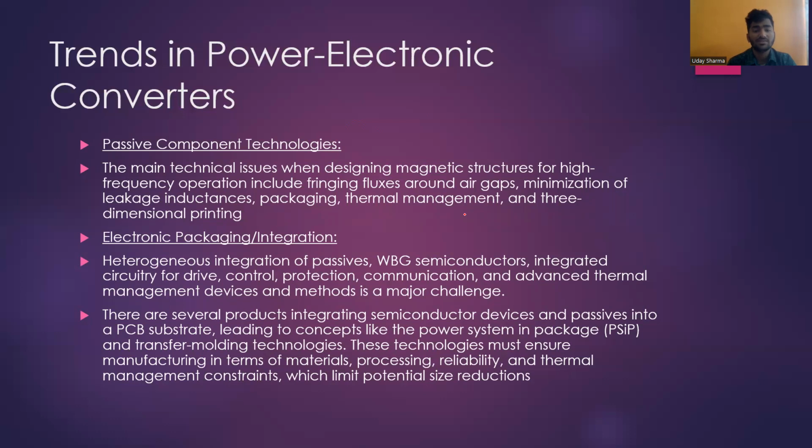Heterogeneous integration of passives, wide band gap technology semiconductors, integrated circuitry of drive, control, protection, communication, and advanced thermal management devices and methods is a major challenge. There are several products integrating semiconductor devices and passives on PCB substrate, leading to concepts like the power system in package and transfer molding technologies. These technologies must ensure manufacturing in terms of materials, processing, reliability, and thermal management constraints, which limit potential size reductions.